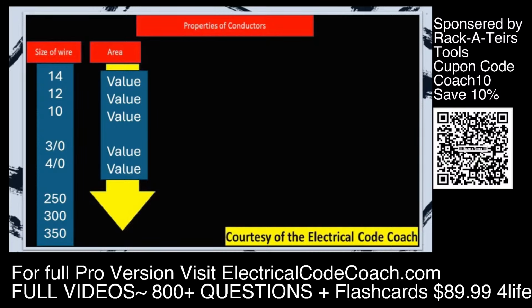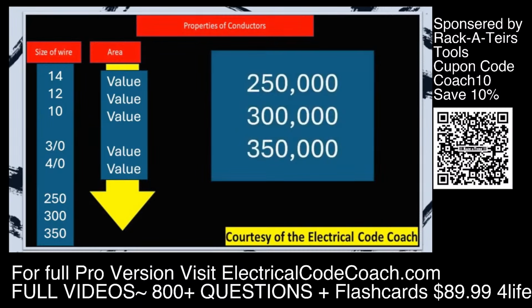You'll notice when you get down to 4/0 that the values stop. And the reason is because the left-hand side of this table, the 250, 300, and 350, are already showing you what the circular mils are in kcmils. So we have 250,000, 300,000, 350,000.